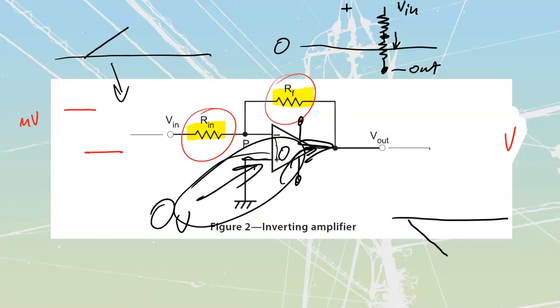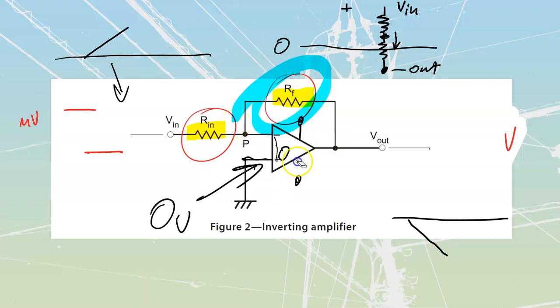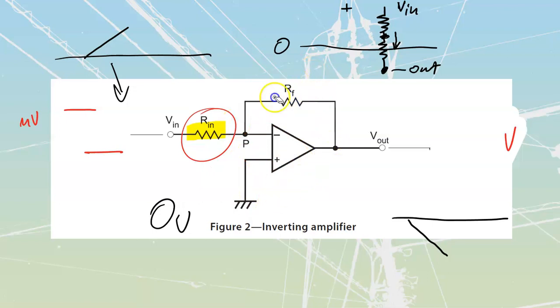The important thing to note is that this RF is really going to control a lot of how far we're going to drive that voltage down. The bigger the value of RF that we have, that would mean the larger the resistance that I would see in this section over here. That would mean the greater the value of voltage that I would have to drive out here on my inverting lead in order to drive that out. So this is just our operation, explained in an easier to follow manner than going through all the, you can go through calculus and you can use summing and things like that to cover them.